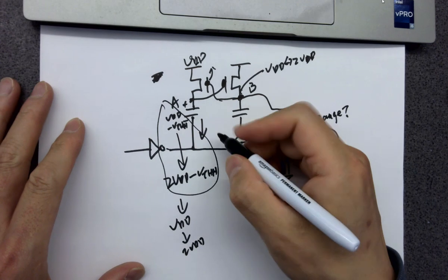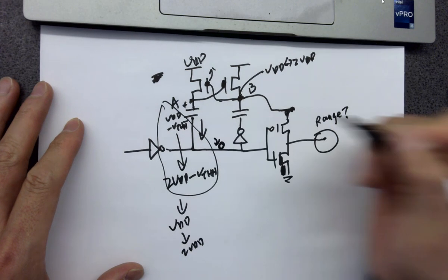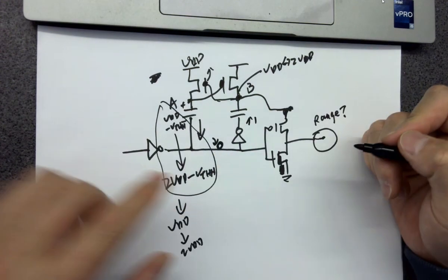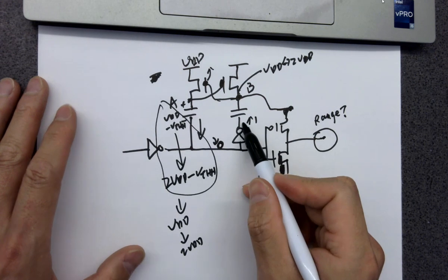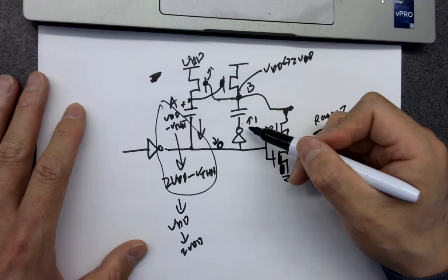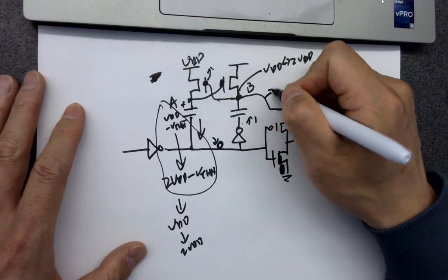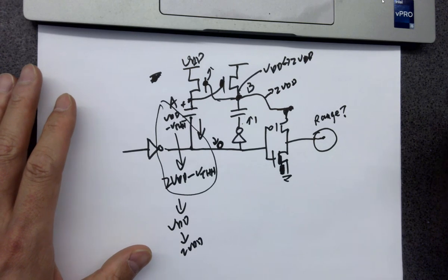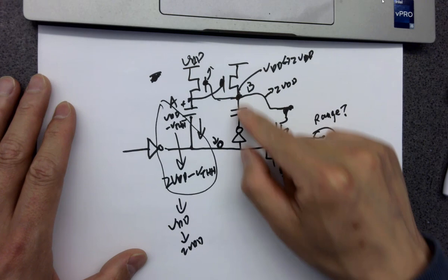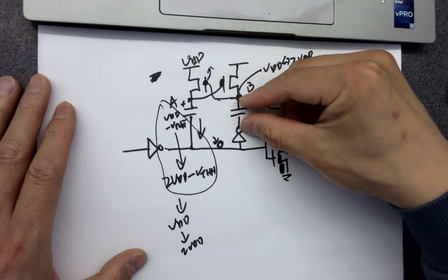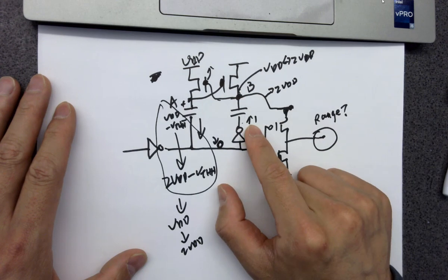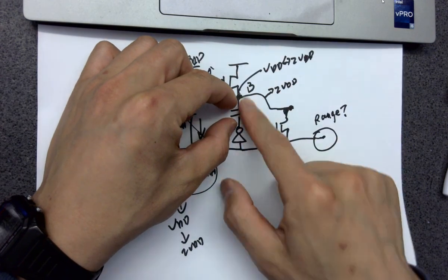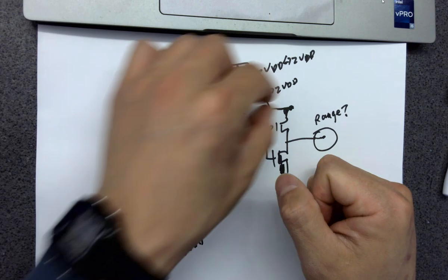So when this is 0, or at least it's pulling down to 0 at this point, and this one is going up to 1, because there's an inverter in the middle. So if this is pushing, the voltage here becomes 2 VDD. Why? Because in the previous cycle, when it was pulling, it pulled the VDD to this plate. So after that pulling, it already has a VDD across it. So when it's pushing 1 VDD to it, it's adding the voltage to 2 VDD.